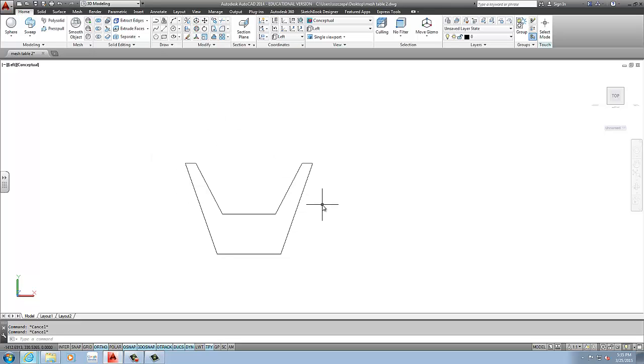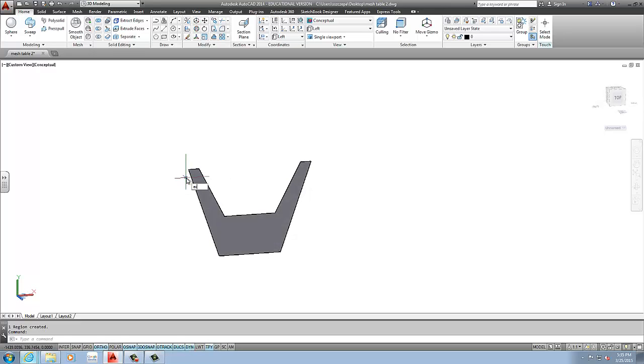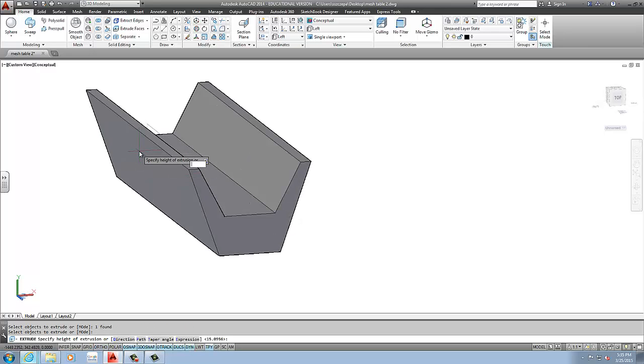While you're doing this, I'm going to take the 3D rotate and use it. I also recommend typing in distances. Then I'm going to use the region command, look for it, and extrude this out by 2 inches, so you can't make a mistake.